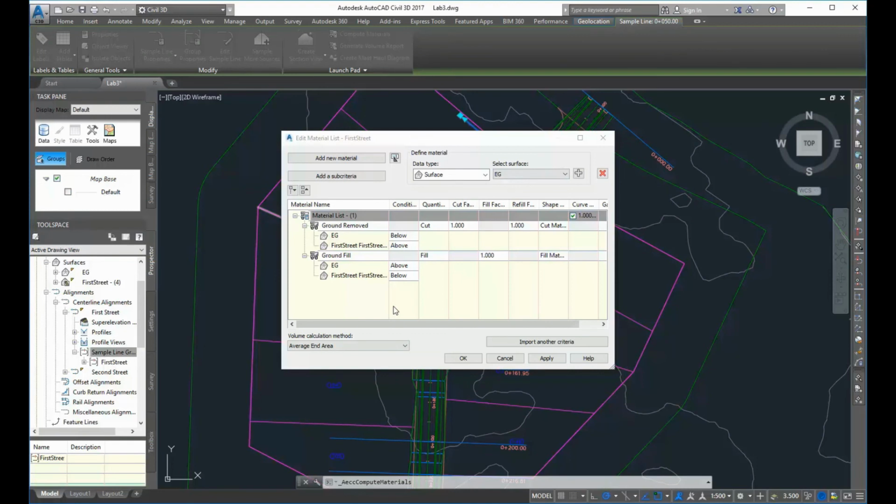So when we do a project, we're generating material when we're cutting it, right? So you can think about areas where we have to bring the existing ground down and cut it away. We would move it over to a stockpile. And then there are other areas, like the one we just saw in the section view, where we're filling the material. And right now these factors are set at 1. We're going to talk more about it in class, but I just want to make sure this is clear.